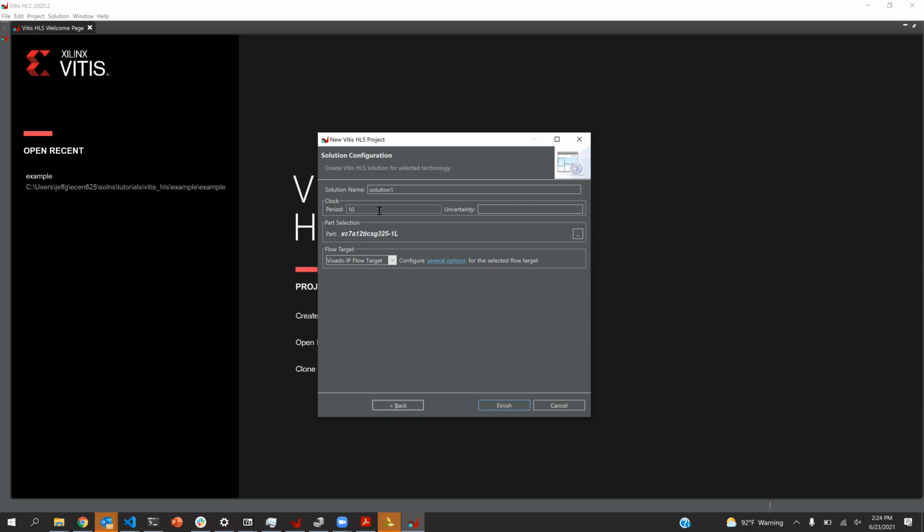If I said, go make your Verilog run at a clock that's twice as fast, you'd have to start ripping things apart, adding new states and new flip-flops, splitting stuff up between different states in your state machine, and restructuring all of your code. You don't have to do that here. You just change a drop down. It's kind of neat when things are auto-generated for you.